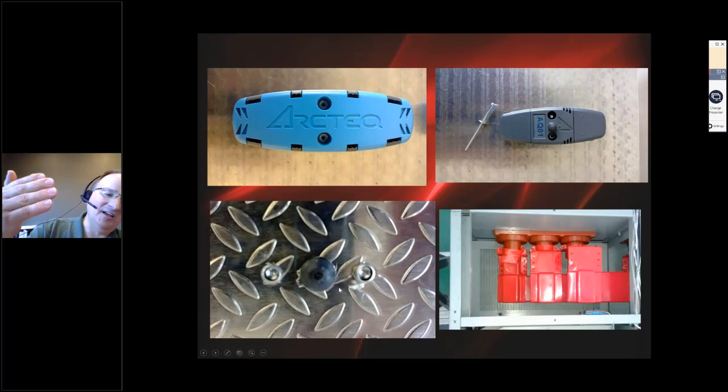The sensor itself is on the other side of this piece of steel, where we just drill a hole and insert the nub into the compartment that we need to detect the light from. A very common method of installing our particular light sensors. In the bottom right here, you can see a light sensor pointing up, in this case, towards the bus. So light sensor positioning and installation is both a science, I would say, and an art. We have dedicated resources at Tech4 just for determining light sensor positioning based on our high-powered test lab results.